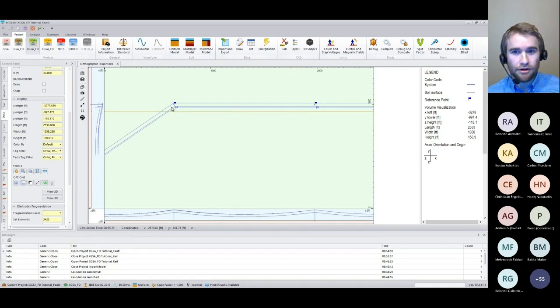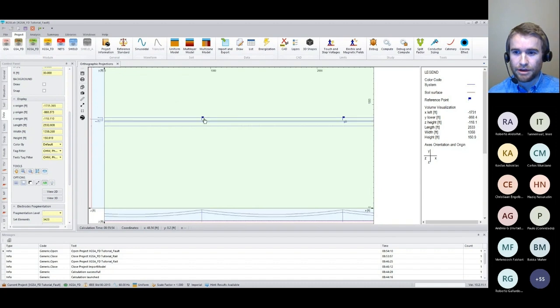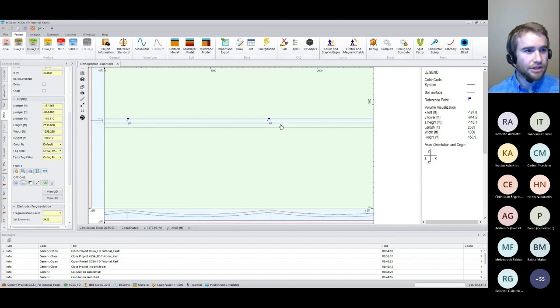We also have a concern of faults happening for each of the towers in this corridor. One of the advantages of Scheduler is that it allows me to put a reference in at each one of these points. If I go along here, you can see I've placed a reference on each one of my approximations of my tower model. That's just a simple linear conductor, almost like a monopole. It's a relatively thick steel pole that's embedded into the earth, and that is what I have flagged as a reference.